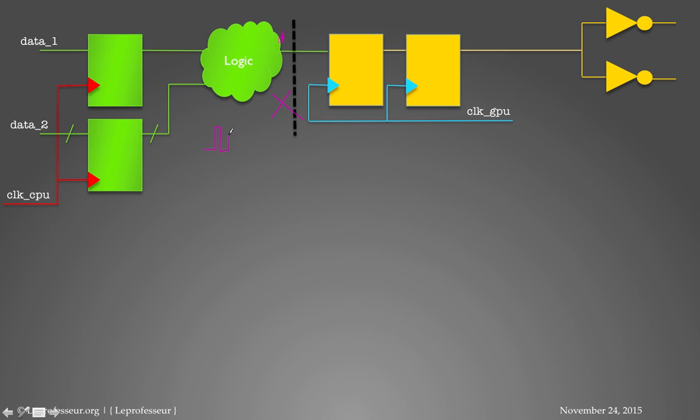That's a typical nature of a combinatorial signal, that it might have glitches, or it will go up and down too quickly. So now these glitches will cause a problem. These glitches will cause the flops in the receiving clock domain to go into the metastability state too often.